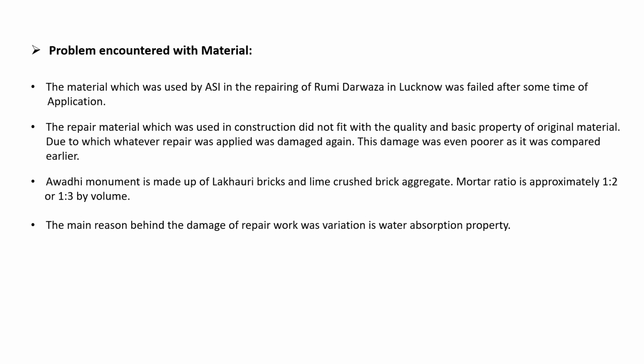The Awadhi monument is made up of Lakhori bricks and lime with crushed brick aggregate. Mortar ratio is approximately 1:2 or 1:3 by volume. The main reason behind the damage of the repair work was variation in water absorption property.